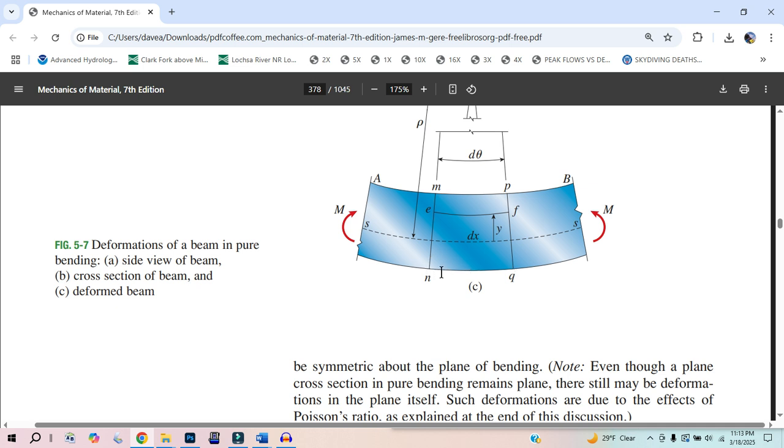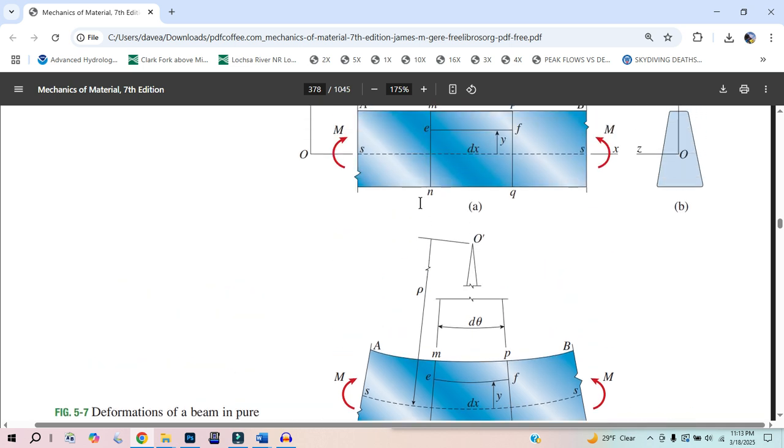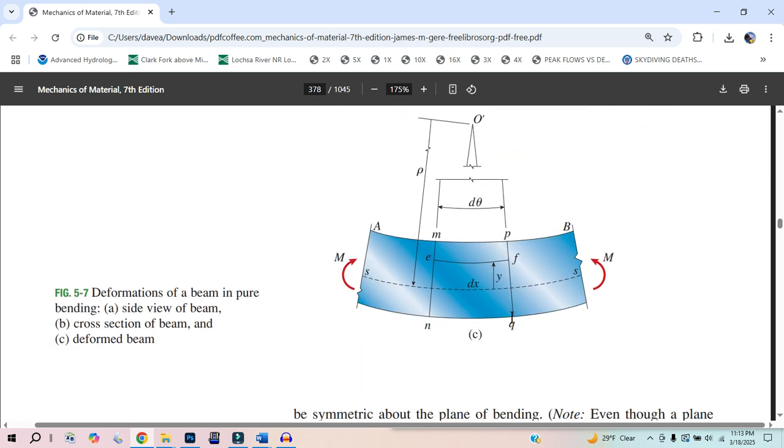So if I say that this length is the neutral length plus some change in length, that's also very good to get yourself into. Sure, this is longer, but how do we explain that when they want us to use the term strain? Well, it's longer, but longer compared to what? Longer compared to its original length. Okay, so if this is the original length, then it stretched out. Let's say it just stretched out that much. Cool. And then strain, by definition, is like the percentage that it stretched.